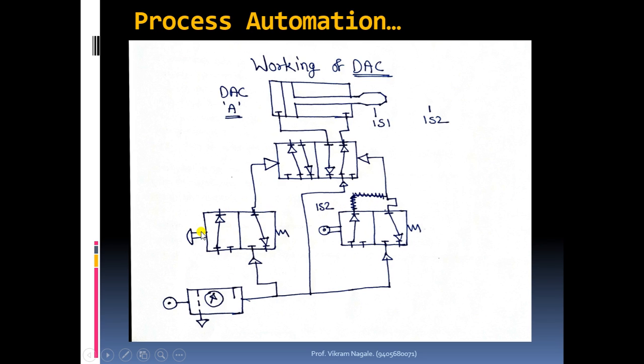Okay, so here see what will happen whenever we are pressing the push button of this valve, that we will discuss here. So whenever we are pressing this push button, and as it's spring returned, the block will slide inside this casing of the valve, and the connections will be given to the left side block.